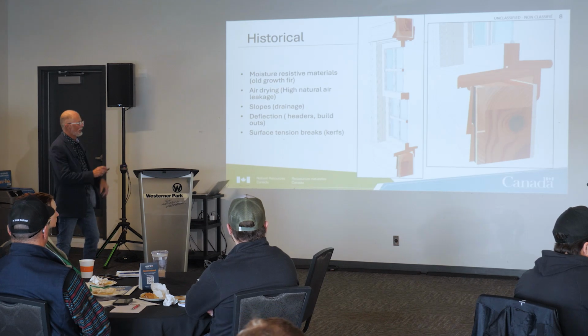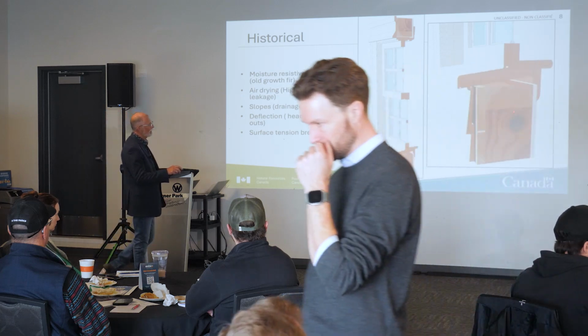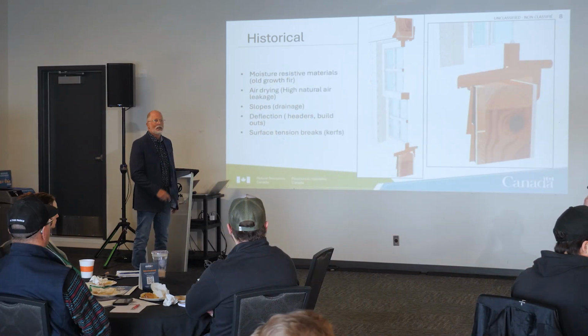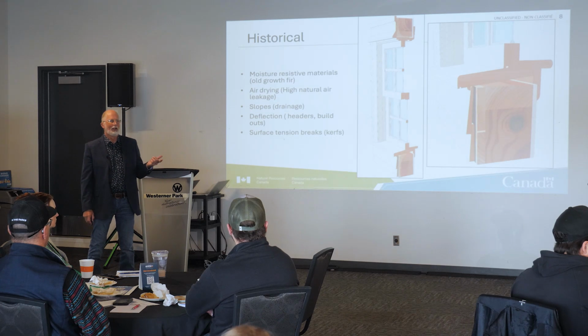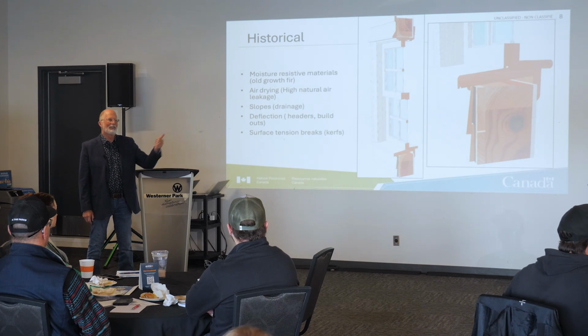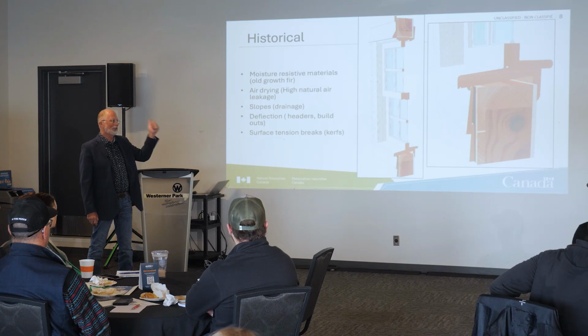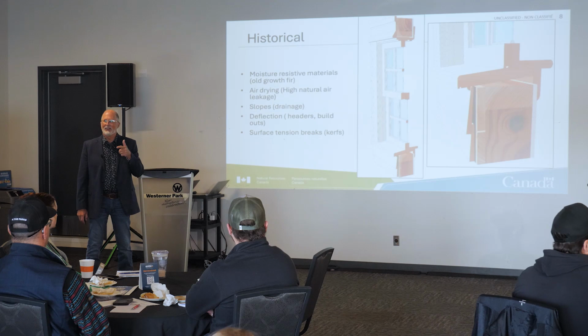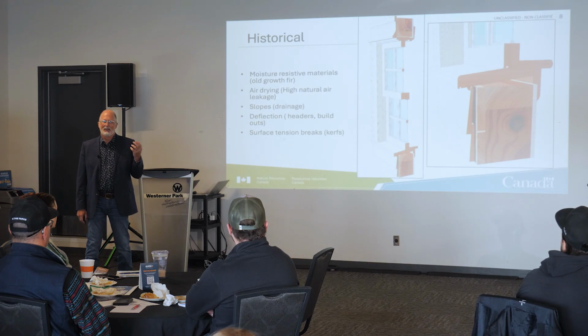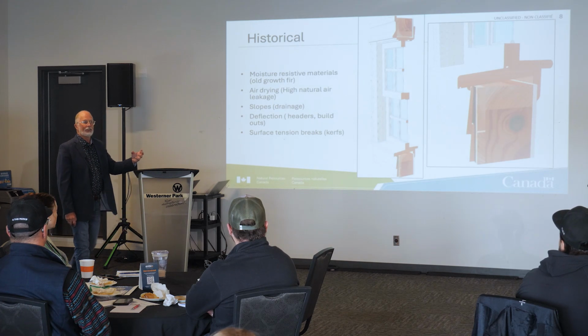The other thing that really changed is what kind of lumber was used in 1920, 1930, 1950. We had fir. You ever renovate a house and pull the fir out of it? You ever try to drive a nail back into it? You've got to pre-drill it to nail it. It's just like rock. And old growth fir versus new growth fir.